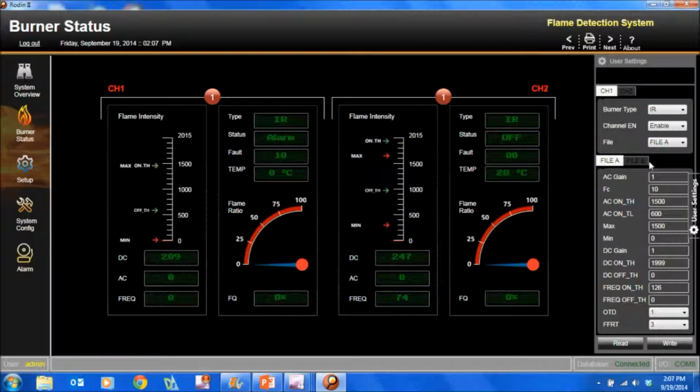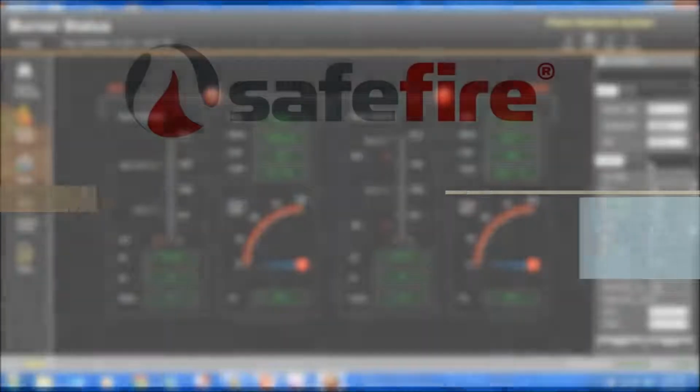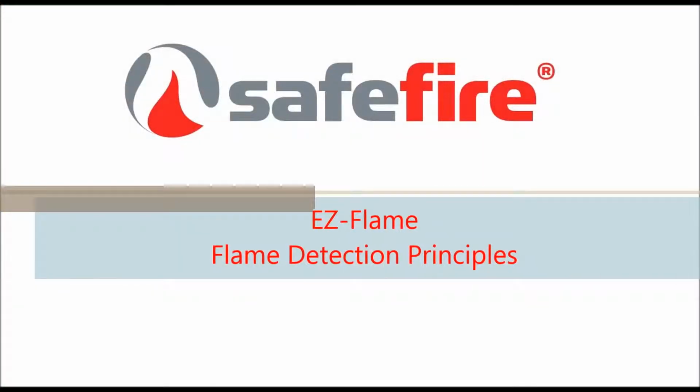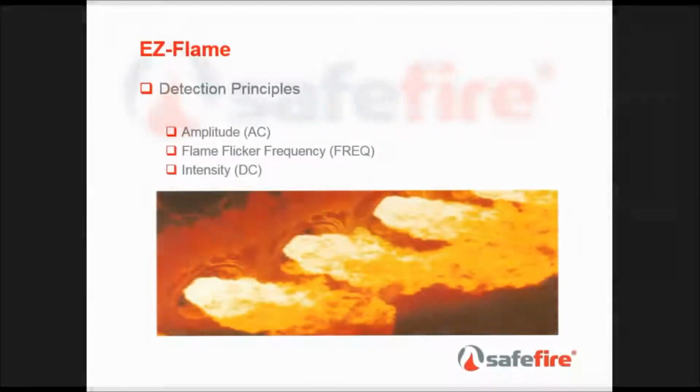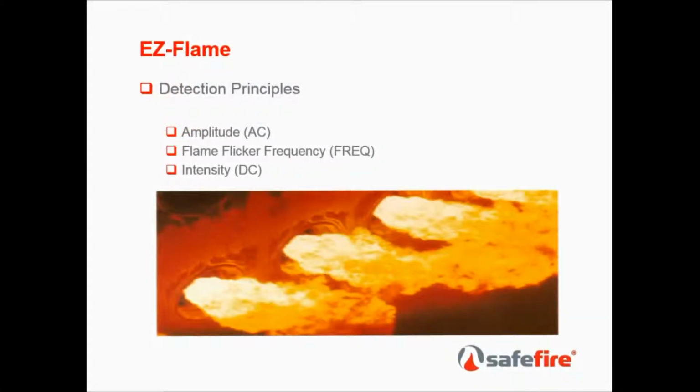But before we go into how to modify the parameters, we must understand how the Easy Flame system determines if a flame is on or off, as well as the definition of each parameter. The Easy Flame system utilizes 3 detection principles to determine if a flame is present or not, and those are amplitude, flame flicker frequency, and intensity.